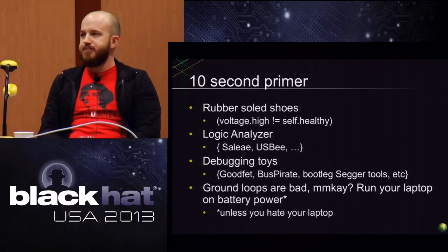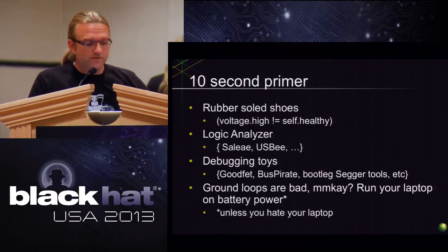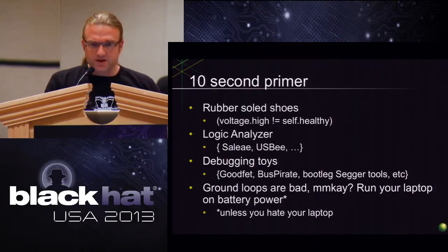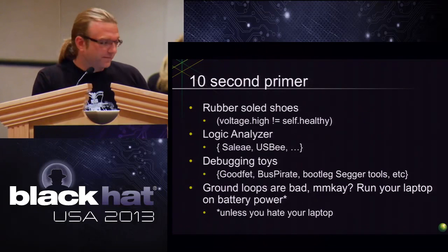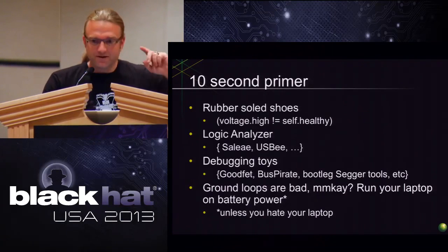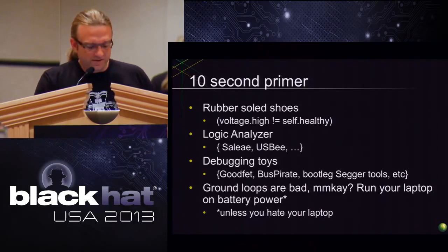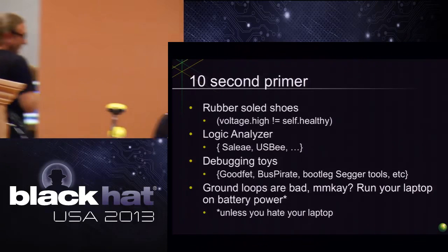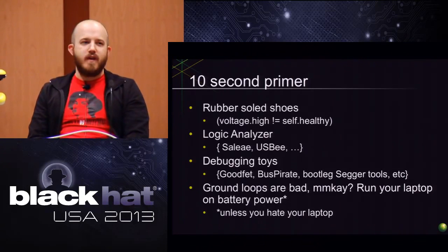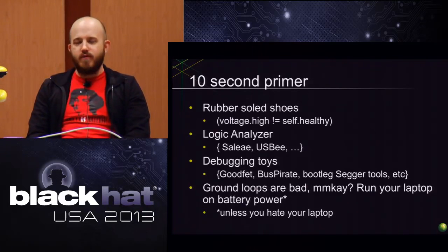Yeah. And the last kind of pro tip that we've got before we really get into the meat is if you're working on high voltage or typically almost any embedded system you see, if you are powering that device and you're running ground on the same plane that you're running your device, like if we're running 110, your laptop doesn't like that, and you end up doing things like frying your USB ports. If PCBs were designed correctly, that would never be a problem. But when you get into debugging interfaces and stuff like that, there's a couple of them out there that are known for letting you electrocute yourself or fry your laptop.